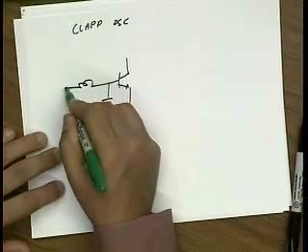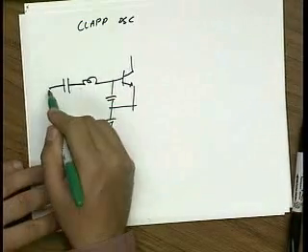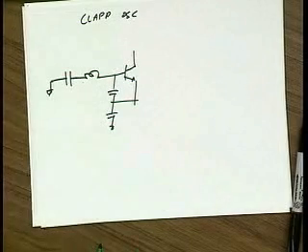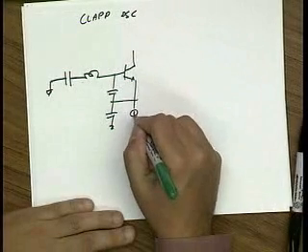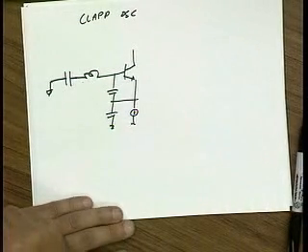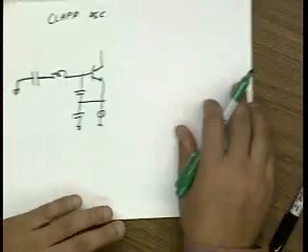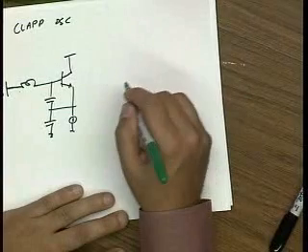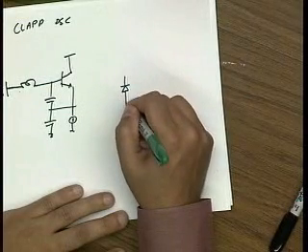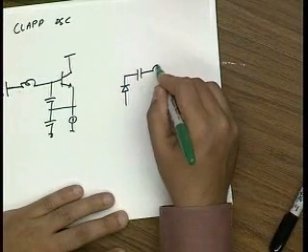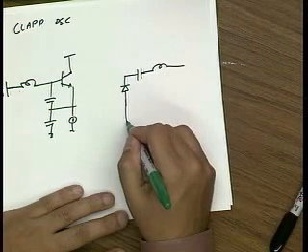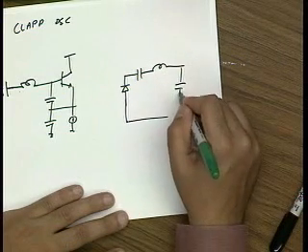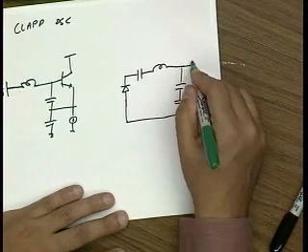So here I'm going to put another capacitor and ground it, and you say, well, big deal, why would you do that? Well, this is a nice way to build a variable oscillator. This isolation that I get for free, I can use to introduce a varactor.